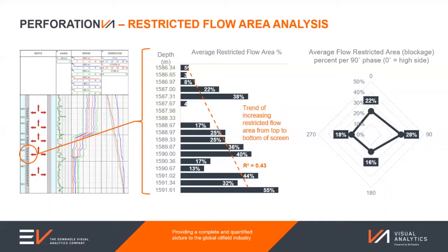So it could be that if you have hydrocarbons coming in at this zone and you're seeing the presence of solids in the perforation base holes, in the perforation tunnels, you could elect to do a cleanup operation, maybe acidizing, maybe jetting, maybe even electromechanical pulsing, or it could be that you simply go and shoot more perforations in that area, knowing that that will increase the well reservoir contact.